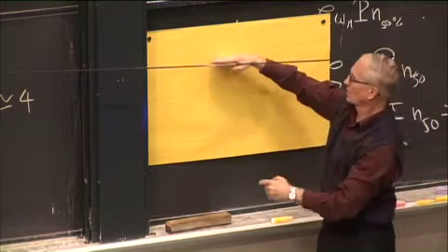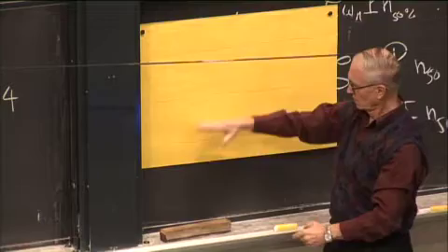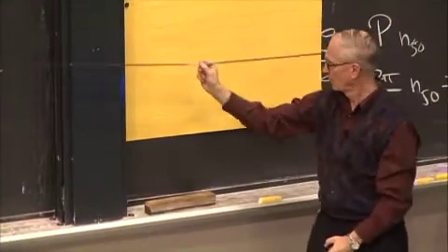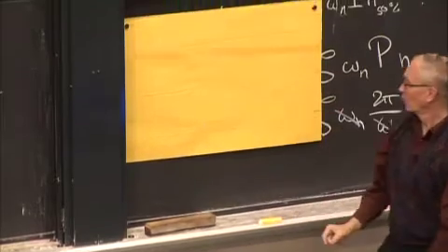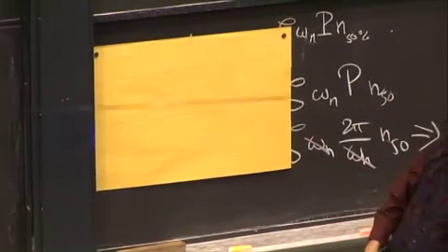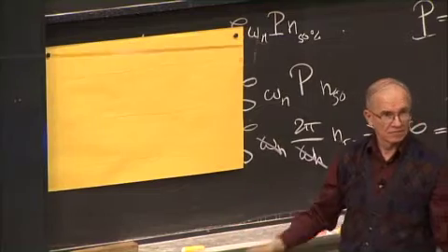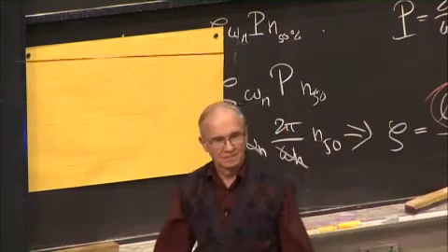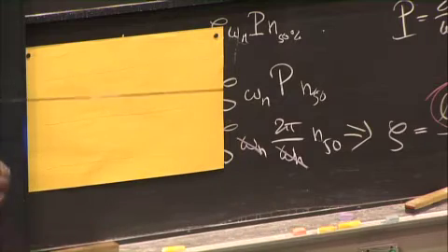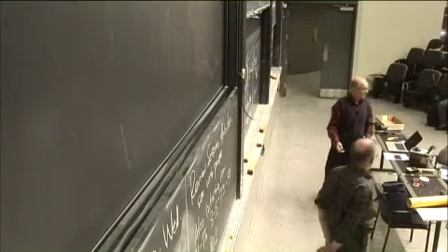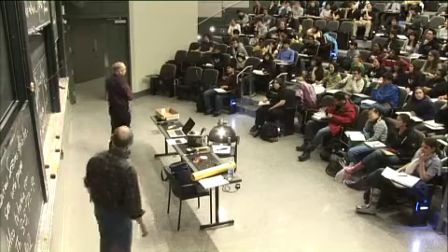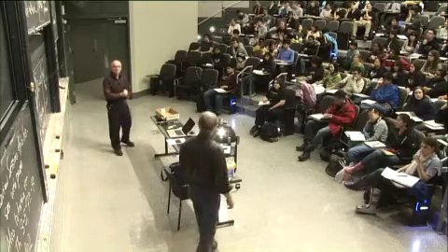So I've tried to make this line up with its mean position. Pull it down to here, it's going to vibrate, and when it gets back to here, tell me how many cycles. 1, 2, 3, 4, 5. About 5? What's the damping? Comes out about the same. 0.11 divided by 5, 0.01 times 2. So amazing. So this mass system and this string have something in common. They're about 0.25 or so percent damped.